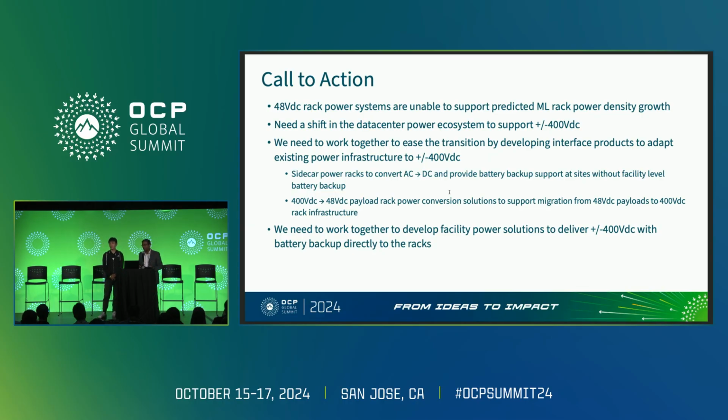I think what we truly need to do is make those products more commercial and generally available, because there are really fundamentally 2 aspects to it. One is figuring out what that large-scale AC to DC transformation looks like at a multi-megawatt scale, right? Because obviously we don't want 500 kilowatt SSTs, because then we need to put a ton of them in a 100 megawatt data center. We need to get into the 3, 5, 6, 9 megawatt scale SSTs that can convert power at large scale.